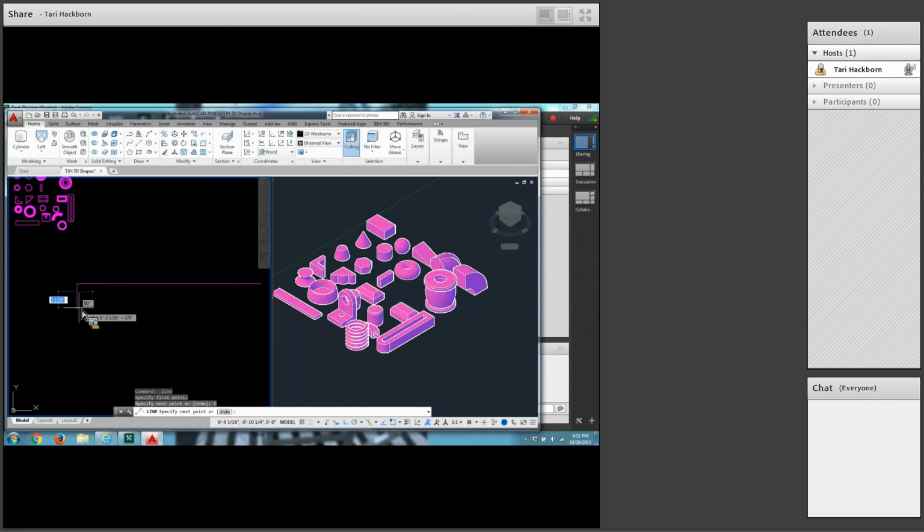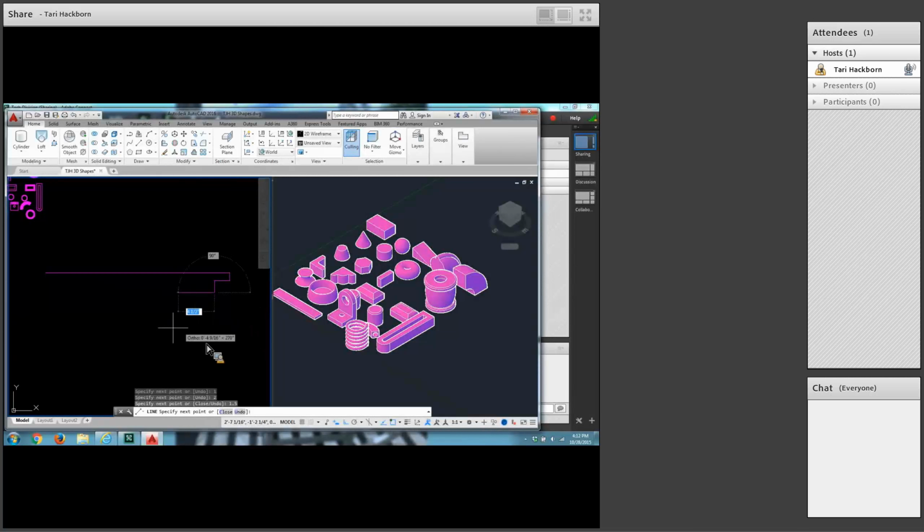Now I have dimensions after that, right? Well, if I want to match the text, I have to actually do the other side. Let's just erase that one, because it says move to the left 2 inches, and I would have had to move to the right 2 inches from there. Okay, so come down 1 inch, move to the left 2 inches. Now, how far down do I go? Down 1.5 inches, to the left 1/2 inch, down 3 inches.